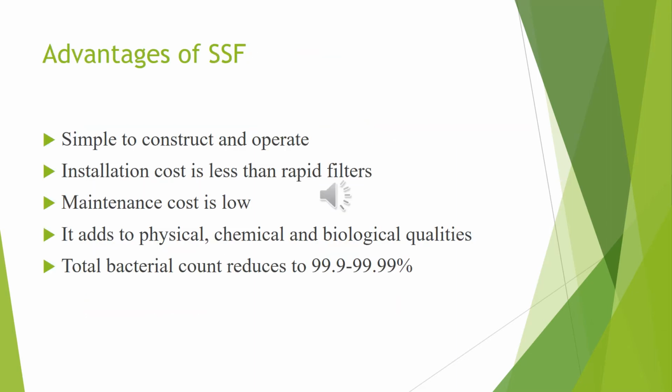Coming to the advantages of slow sand filters, they are very simple to construct, and very less trained staff is needed to operate it, and very less amount of money is also needed to install it. Now the maintenance cost is also very low. It adds to physical, chemical and biological qualities of water, and the total bacterial reduction rate is from 99.9 to 99.99%.